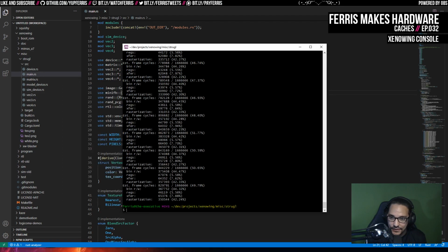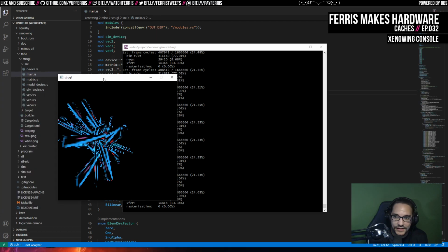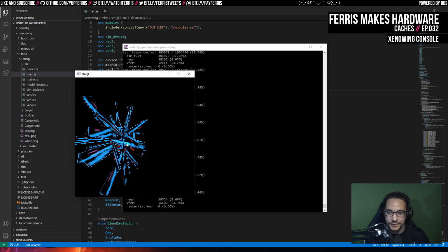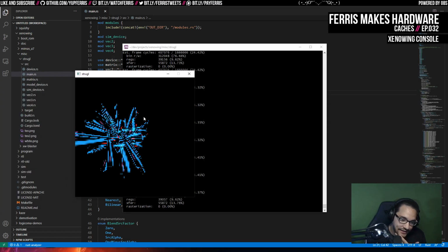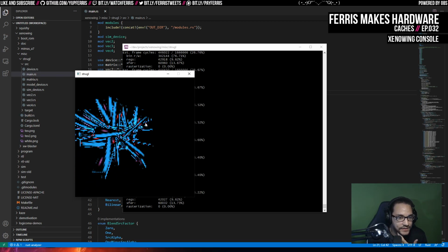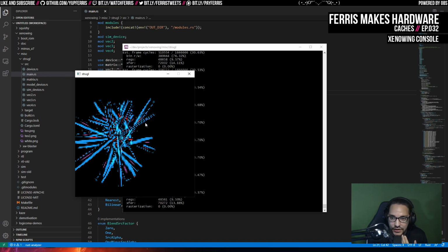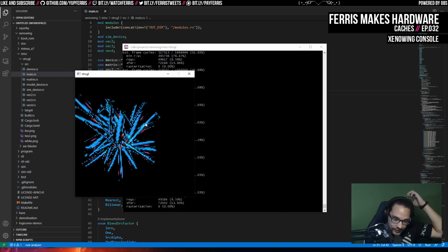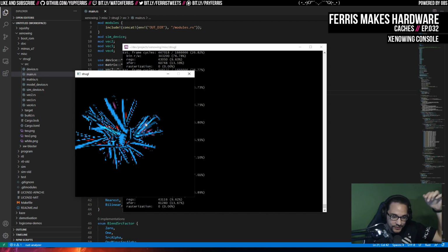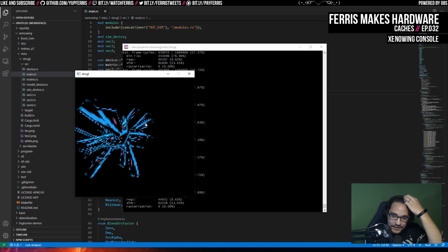And there's a few reasons I built this. I'm also going to show a faster version of this and explain the difference. So this is a bit faster, and you can see a little more clearly what's going on. So basically, what I had before, which I bootstrapped on stream, was a way to drive the GPU where we actually talk via a simulated UART to the CPU and then forward commands and data transfer with that mechanism.